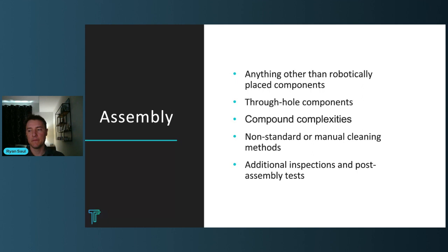This could be a functional test where you provide a test process for your manufacturer to review. It could be flying probe or ICT. I would just consider, do you really need these things for the stage of the build that you're on?